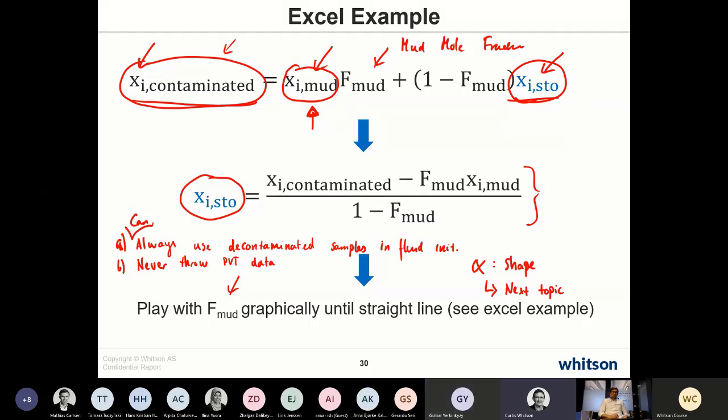You know, it's very simple. If you have reliable PVT data on samples with lower contamination level or zero contamination level, don't waste your money on getting new PVT data on these highly contaminated samples. I mean, if you have this data already, or low contamination levels or zero contamination levels, I wouldn't spend money on getting new PVT data for these very highly contaminated new samples. If you don't have any of that other kind of data, the only data you have is with samples with 50, 40, and 30% contamination level.